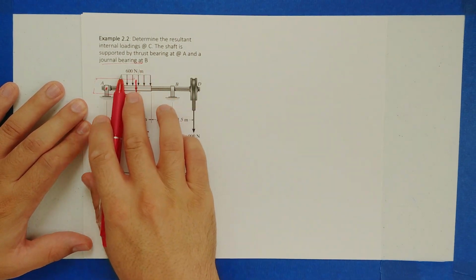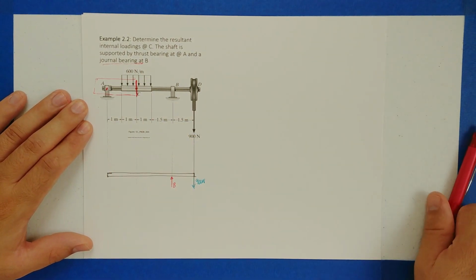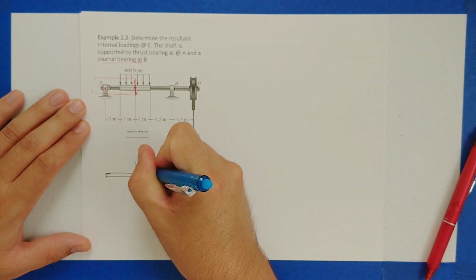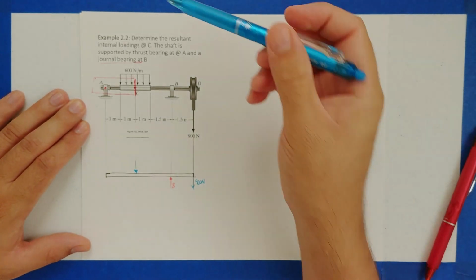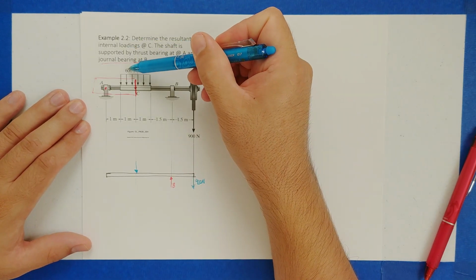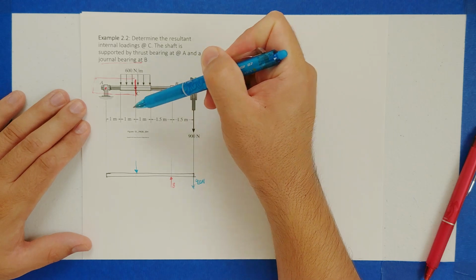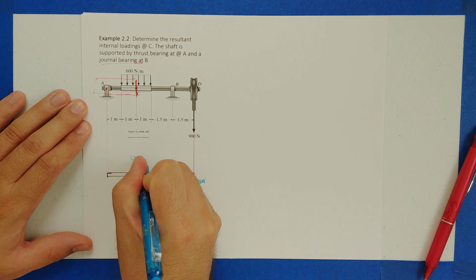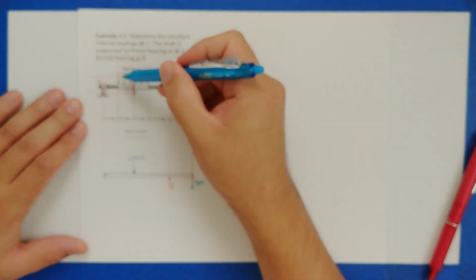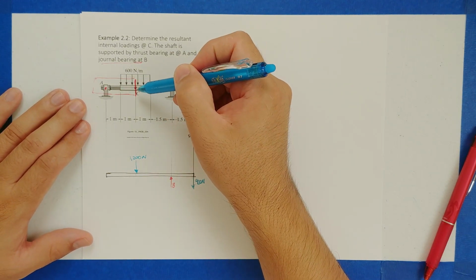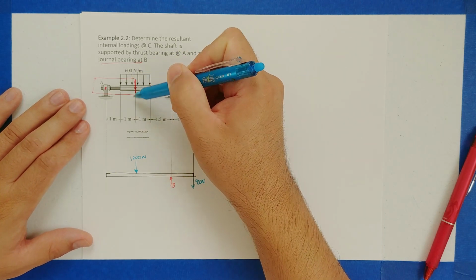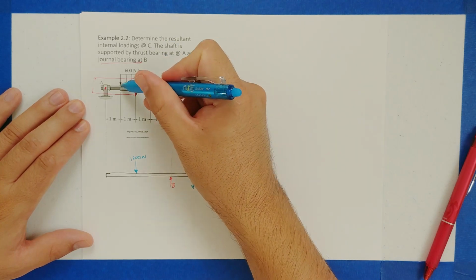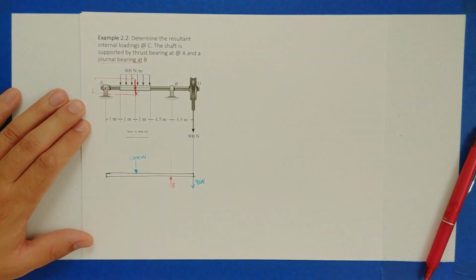So next I have this distributed load, but I don't want to use that. Instead, in my free body diagram, I want to replace it with just a point load. The way we do that is we get the area, right? So this one is 600 newtons per meter because there's 2 meters. 600 times 2 is 1,200 newtons, and it would go right at the center of this area. This being a rectangle, it's pretty easy to see that the center is right at point C, which is 1 meter each way from the start of the distributed loading.